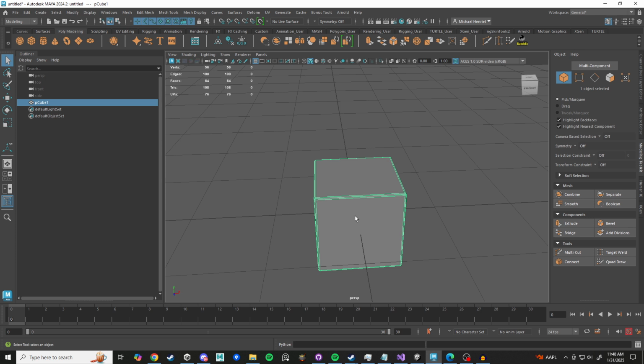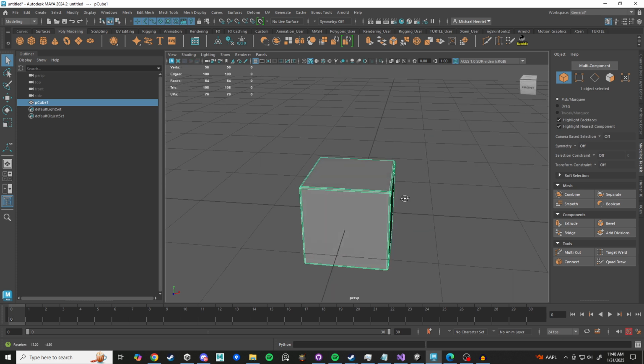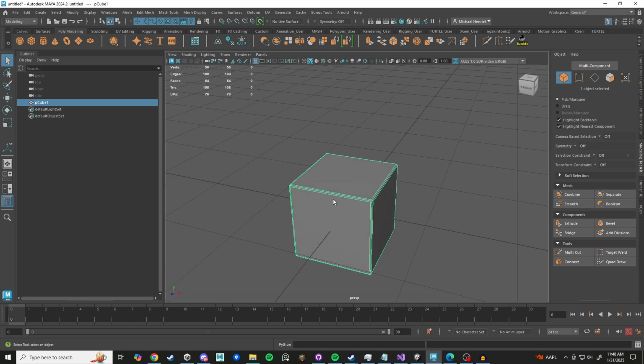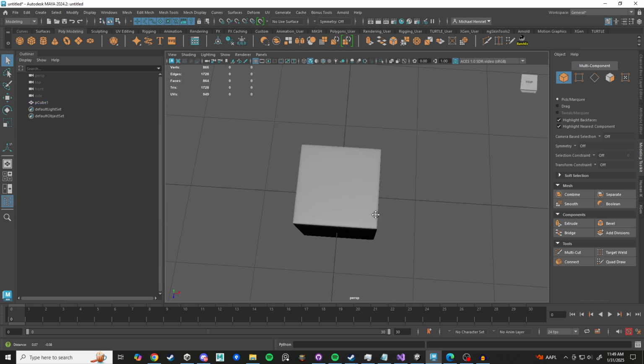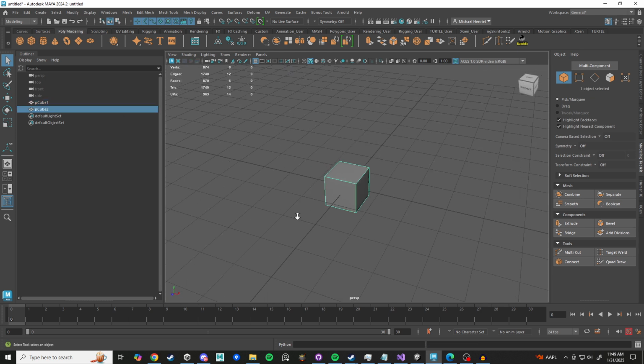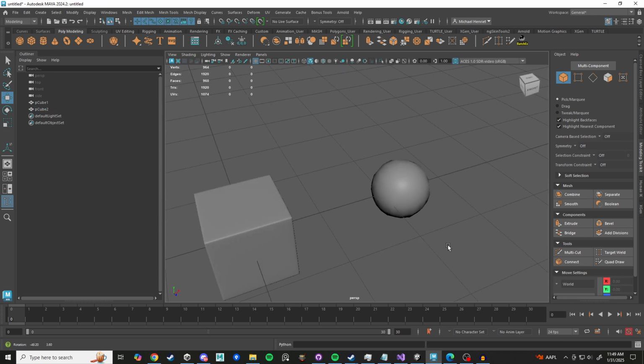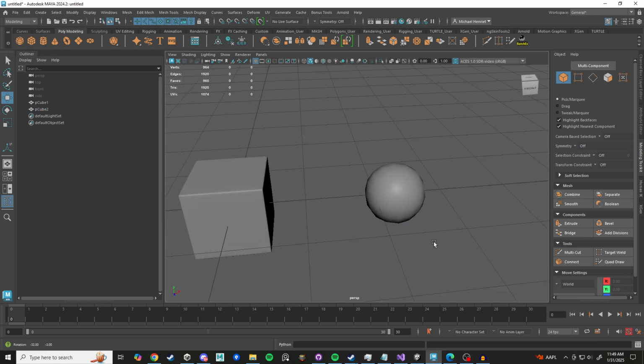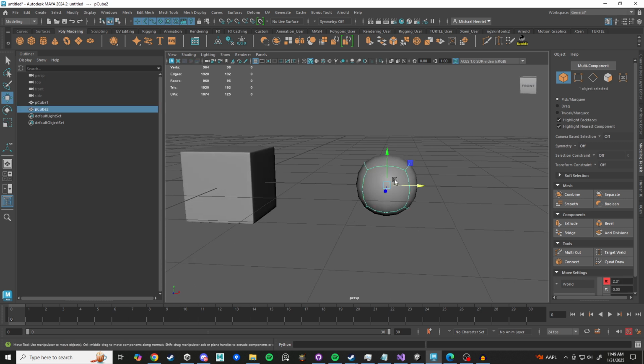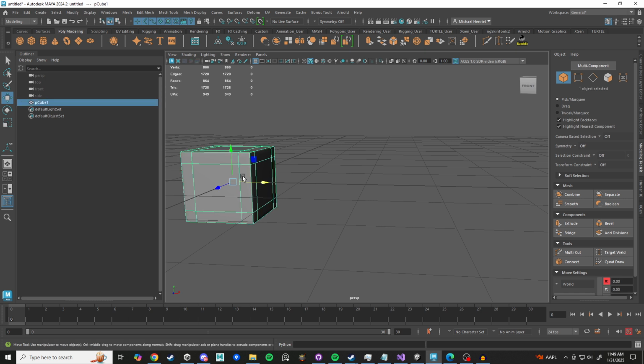If you are exporting something to ZBrush, you want to make sure that it's prepared for subdivs in there as well. So like if you export this cube and you go up in subdiv levels, it's going to still deform nicely. If you brought over this cube and then subdivided it, boom, you have a sphere now. That is not a cube, right? So subdiv modeling is kind of getting into that mindset, like how is my shape going to look once it is going through subdiv levels, right?